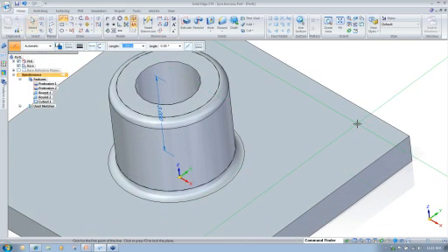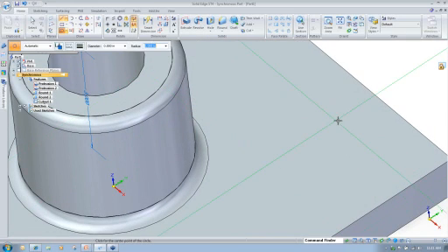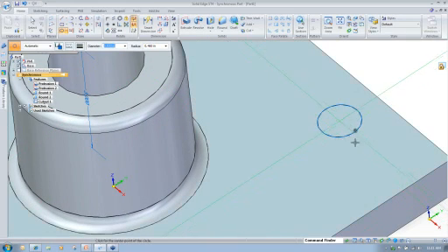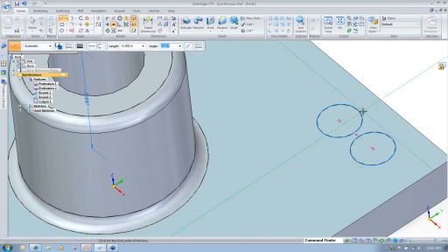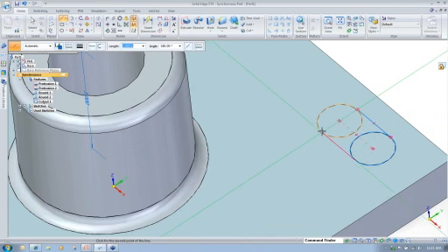So I'm going to come and lock to the plane. So now that I'm locked, I'll start creating some holes again, using alignment, using all of those good habits that we all learned in the ordered environment, still applying the synchronous. I'm going to set these equal, and I'm going to finish off my slot by putting in a couple of lines and making sure that they're attached to the quadrants of the circles. Again, paying attention and good mind to my relationship handles.